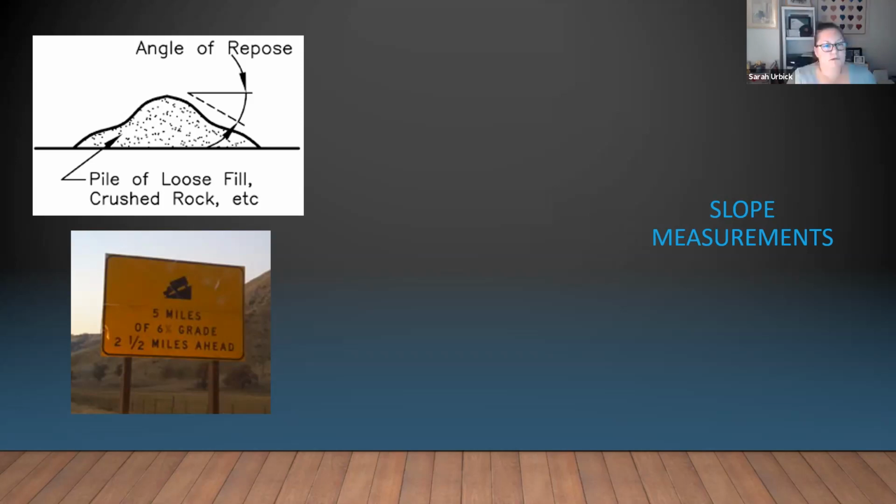Okay. So anybody know where, and I'm thinking a very specific one here, and again I'm coming from the construction side. When we talk about horizontal to vertical comparisons, if we're talking about a slope, a 2-to-1 slope, a 1.5-to-1 slope, so knowing the angle of repose is based on the soil type.